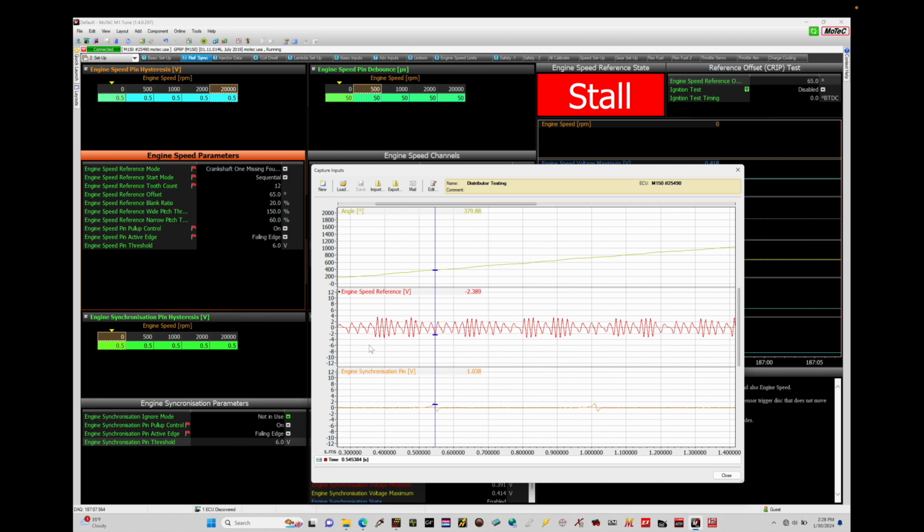and then we only have one on the home. So that's going to allow us to program engine speed reference mode as well as our engine speed tooth count. We also can use our start mode set here as sequential and support sequential operation with the Motec, because we do have this single pulse right here each cycle, which is important because we need that in order to determine the TDC position on our number one cylinder so that we can reference things like injection timing. All right, what we're going to do here is jump into our engine speed reference mode, and we're going to...